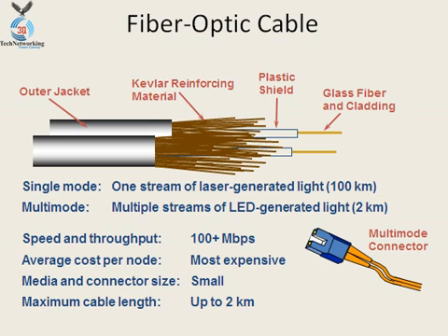For example, if you require longer distance communication, you need to use single mode, and if you require shorter data transmission with a higher speed, you require multi-mode transmission. There are also different types of cables, not less than hundreds of different kinds, especially fiber optic cables. So it depends on the requirement, the environmental factors, and the distance of data transmission.